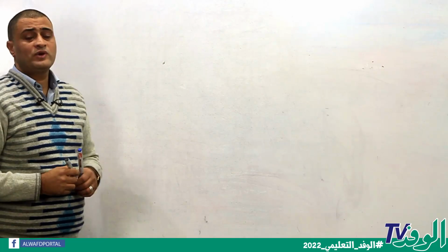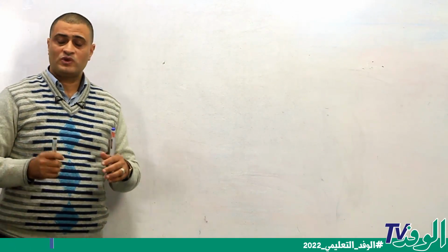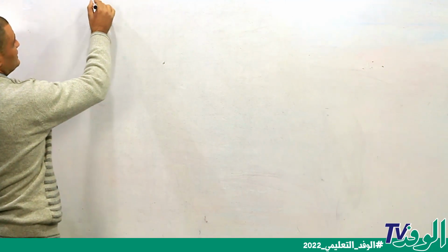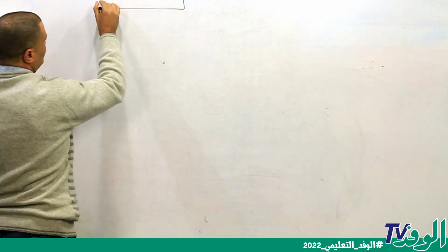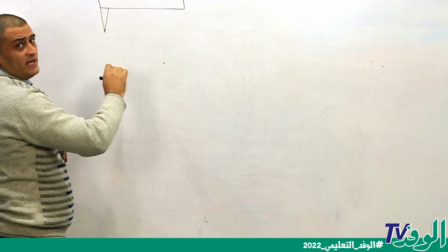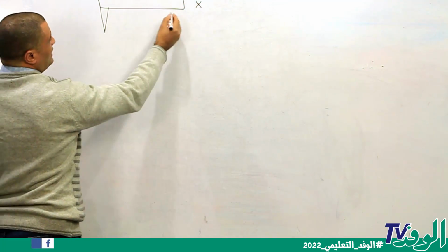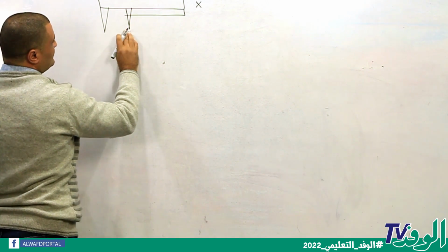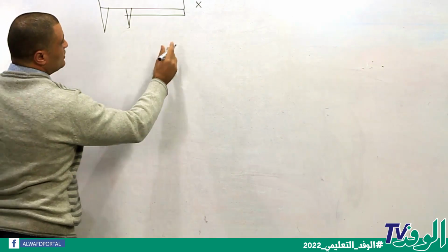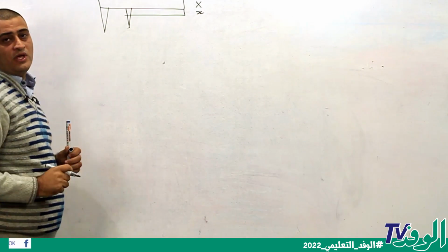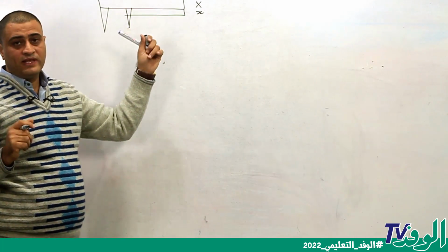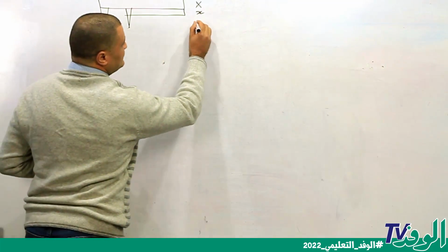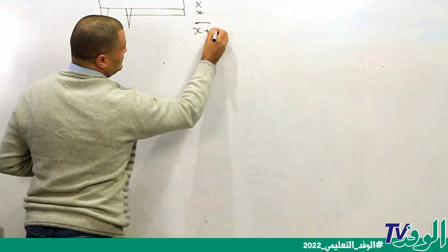Now we'll discuss how we can use the vernier caliper. It's one of the tools which can measure very small lengths. The vernier caliper consists of, number 1, a fixed scale which we call X capital. Number 2, we have another scale which is called the vernier scale. We call it X small. The total reading of the vernier caliper can be expressed as X capital plus X small.